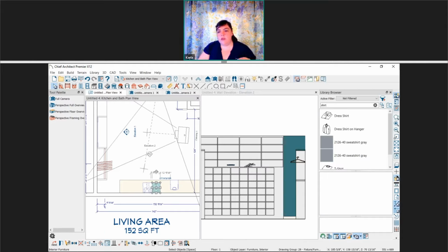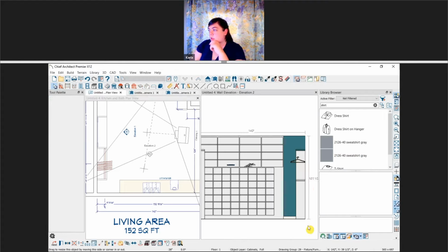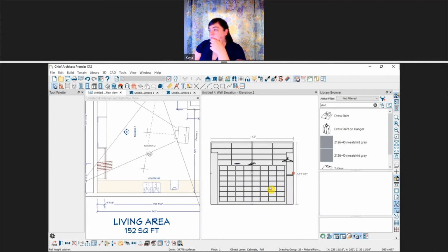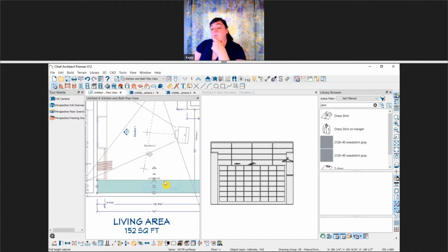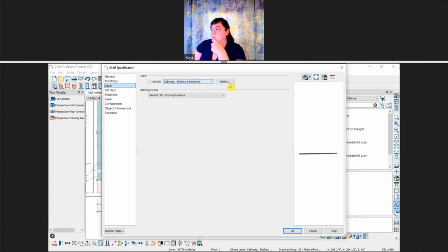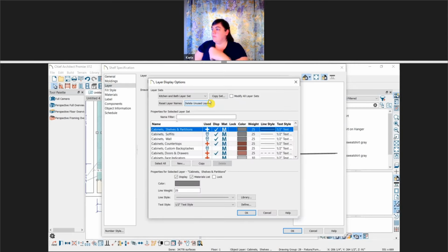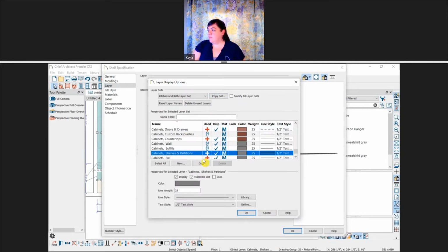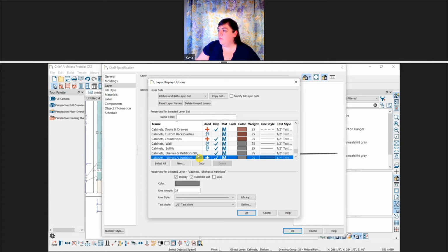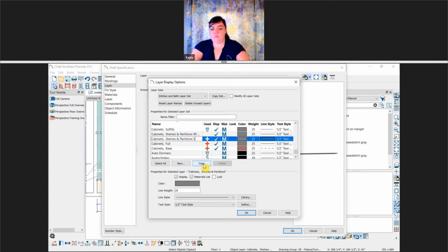Oh, yeah, no. Yeah, there's something that you can try. It's a little bit more involved, but if you want to use the layers, you can designate specific layers for these shelves to go on, and you can lock specific layers so that you can only select maybe the shelf that's at a 24-inch level. So if you have these shelves set up, or a layer table set up to take maybe shelving at 12, shelving at 24, shelving at 36, each one of those layers can be locked individually or combined so that only one of your shelf layers is unlocked, which means you select that one.